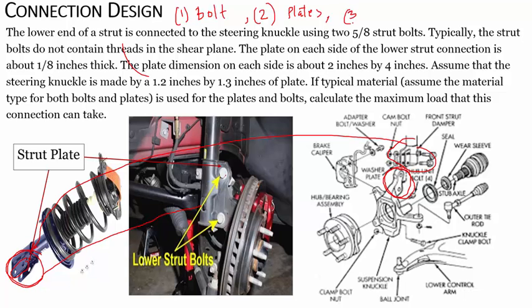And number three, the final type of failure could be because you are cutting a hole there, this place is weak. There is a force going upward, so it probably will not be able to take the tensile load, and it might just crack here and fail because it is not able to take the tensile load that comes on this connection. So these are the three types of failure we can have.